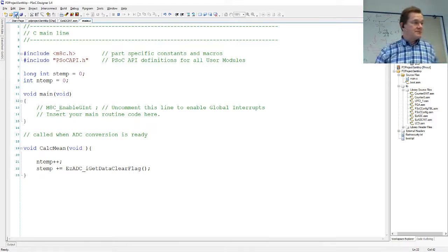Okay, so just a quick review. We were about to do this kind of thing. A sensor goes first to an amplifier, then a low pass filter, then an A to D converter, and then basically you do software downsampling, and finally put the value on the LCD. The hard part was to get all of this correct, since for that to work, you needed to have this switch capacitor filter clock.